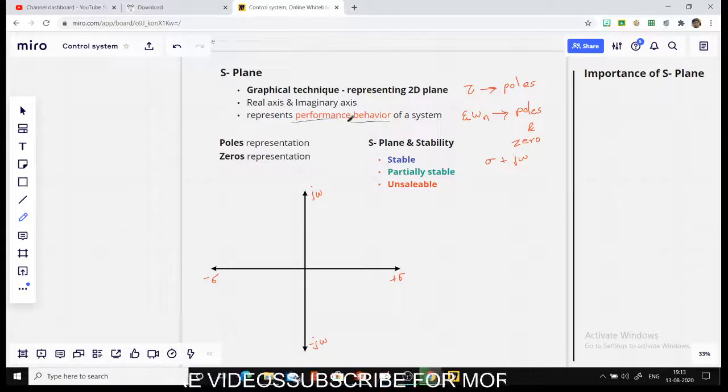Then about the representation, poles will be represented on your system as X. Okay, so a cross is the representation of poles on your system, and a hollow circle is the representation of zeros on your system. Okay, so once you find the values of poles and zeros, you can easily plot those poles and zeros depending upon their values on your S-plane. Okay, positive, negative, depending upon the value.